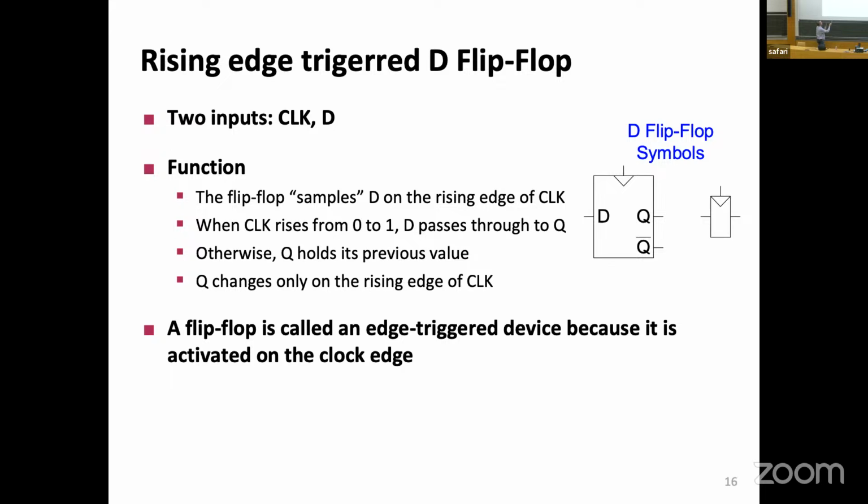Why is it called rising edge? Well, clock has 2 edges, right? If you want to rise a second time, and this is your active edge, at some point you have to fall. Makes sense? No? Okay. And we could have chosen either one. We just have to be sure to agree among all the flip-flops in this circuit that we do it at the same time. Otherwise, life gets a little bit more complicated.